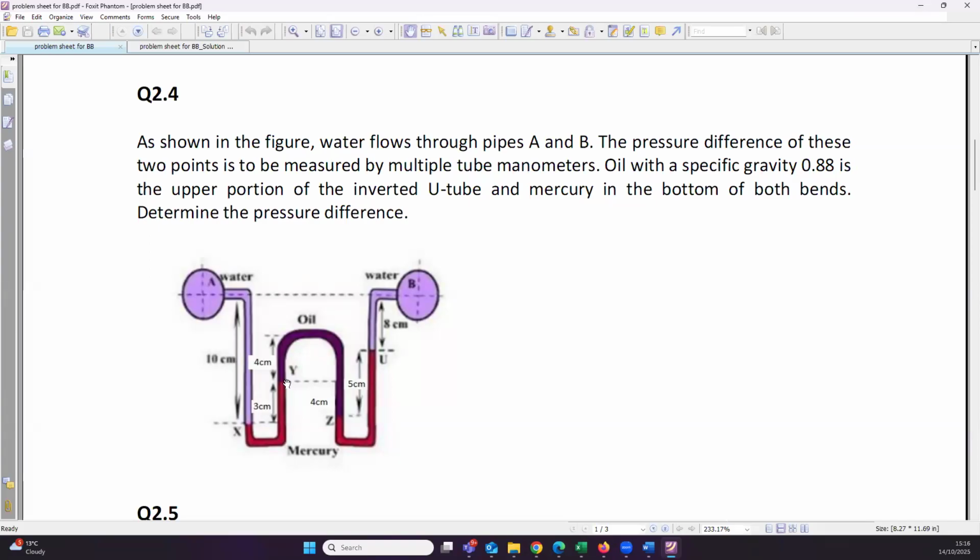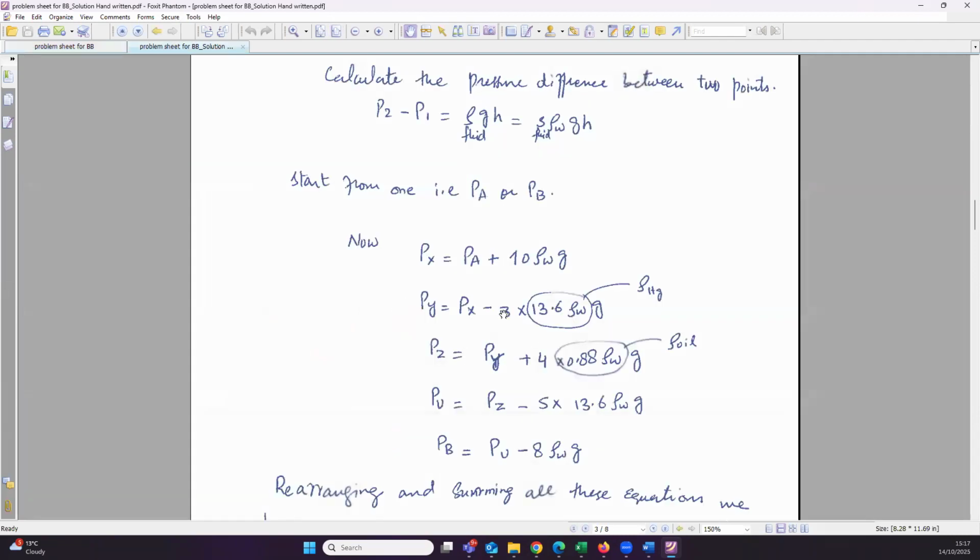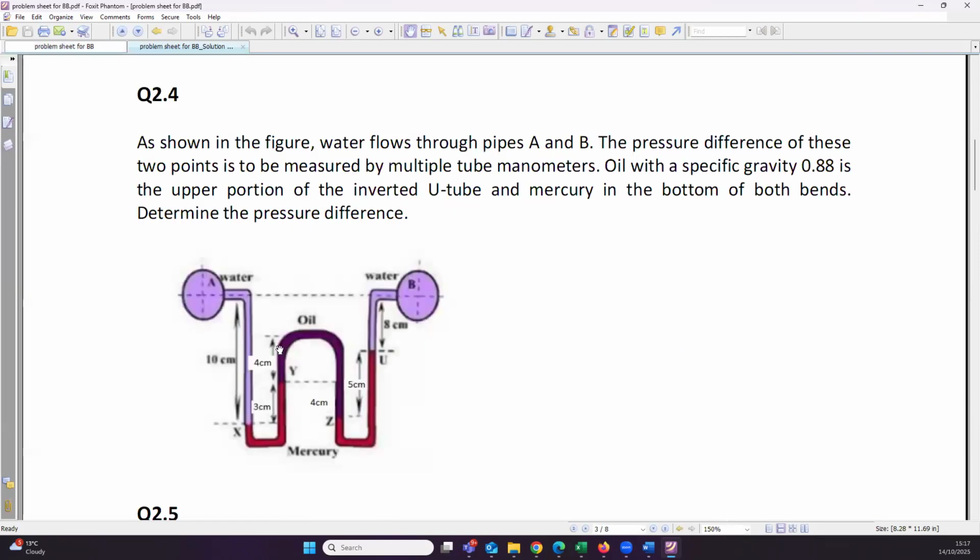But if you go in the opposite direction, towards the height, the pressure becomes negative. It means that it starts to reduce its value. Okay, so again, the pressure will be rho GH, and the H we know is 3, so it will be minus rho GH. The 3 is from the height, it should be 0.03 meter.